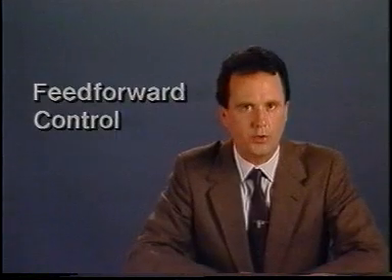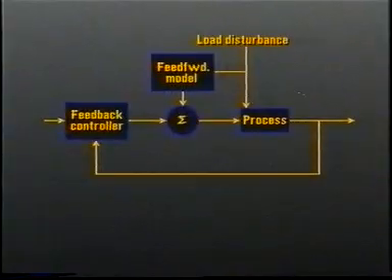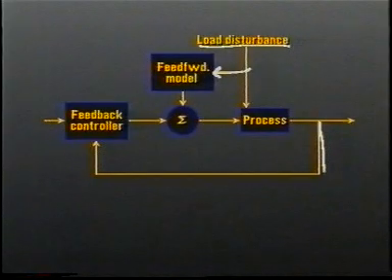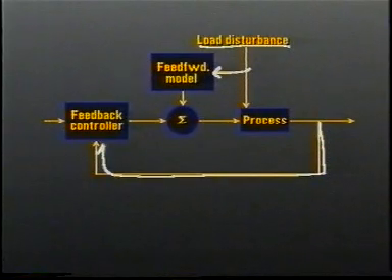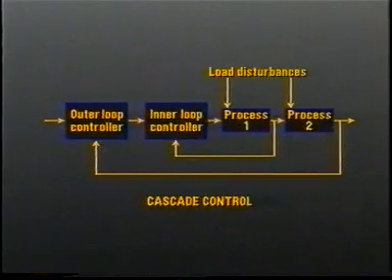Feed-forward control is a strategy that monitors certain measurable and controllable disturbances to the process and transmits changes in their values forward to the controller before their effect has been monitored in the controlled variable. This has the effect in the controller of generating a substitute feedback signal, which produces a corrective action before a measurable error has actually occurred.